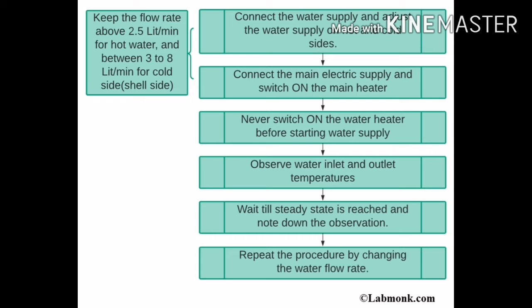On my conclusion, the process of finding the heat transfer rate, heat transfer coefficient, LMTD, and effectiveness of the heat exchanger for both parallel and counterflow heat exchangers has been discussed. Be sure to keep a steady water flow rate and temperature before noting down the readings to get an accurate result. Take note of that. The temperature must be steady, in the steady state, before noting down the readings. Are we clear? Very good. Stay tuned.